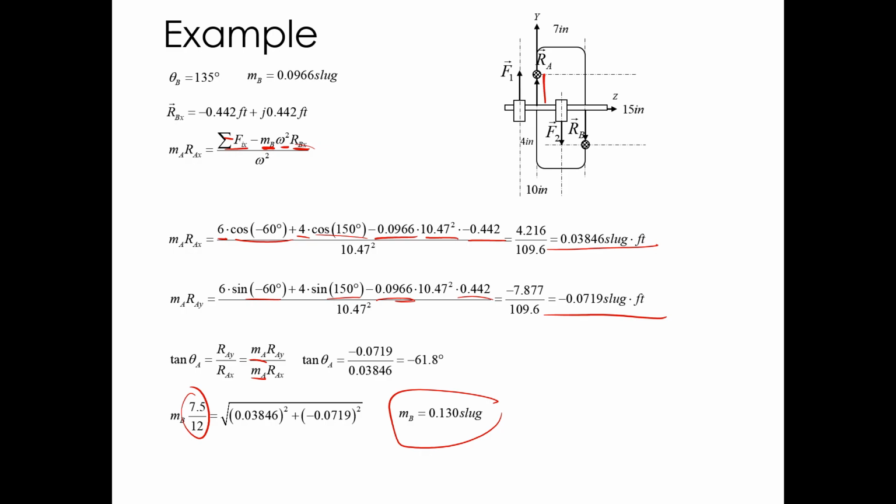Tires also deform when they roll on the ground, so that's going to change it too. So honestly, you're probably just trying to get it better than whatever it ends up being when you put the wheel on the rim. You're not going to get it perfect with compliant bodies like a tire. For something like a turbocharger impeller that's a rigid metal body that doesn't deflect very much, you're going to want to spin that up to the maximum speed it's going to be at in the machine and balance it at that to do the best job of it.